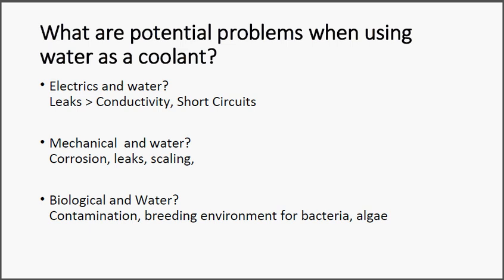The reason is that the antifreeze will help reduce the amount of corrosion that takes place, for example, in the radiator or in other potentially corrosive parts of the engine. Then the other question is, why don't we just use all antifreeze? That might be a good idea. Just put lots of antifreeze in and don't use water at all. Especially in colder climates, you don't have to worry about anything.